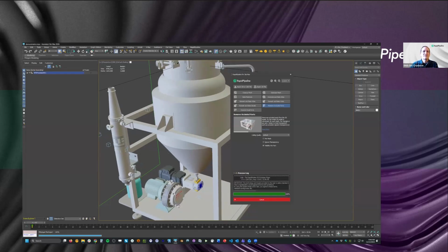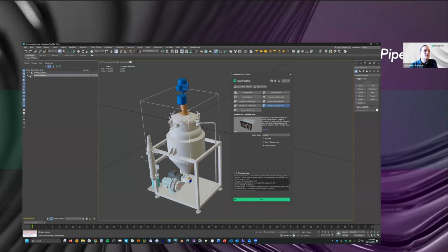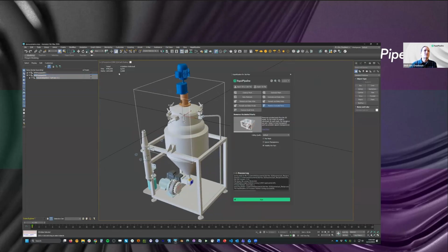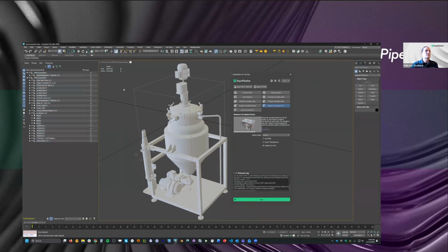So I'm going to go ahead and run this. It's all the defaults, and it's going to go ahead and do all the visibility calculations. And there's returned a new file. And there it is. It's got the file, and it's removed the parts. And we've reduced the triangle count here significantly from the original, which actually, let's see, if we select just the visible parts, I unhid everything. But basically, you can trust me, it removed a bunch of stuff.